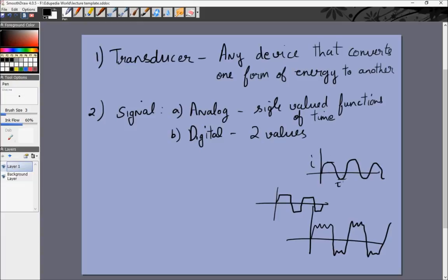So if you take a sinusoidal function like this and a sinusoidal function with, let's say, half the frequency, and a sinusoidal function with double the frequency, and you add them in appropriate combinations, then the sum of them with appropriate weightage to each frequency would ultimately give you either this result or this result. So we can break any type of periodic signal into different sinusoidal functions, and we can also take different combinations of sinusoidal functions to create any form of periodic function. So when you have a signal like this or any complicated periodic function, that can be seen as a sum of many sinusoidal functions of different frequencies taken in different proportions.